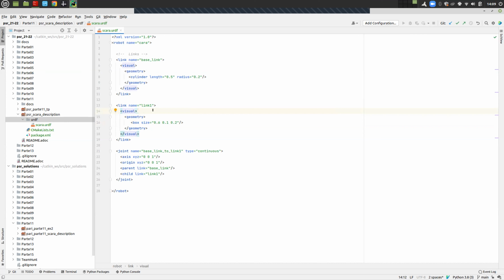So for example, you have some strings like here, which you can pull, and when you pull, it goes like this. And then you have some other strings here, which you can pull, and it goes like this. So this is like a spherical joint, or almost spherical all the way, but this is very hard to do in robots. And not only the actuation itself, but also, for example, the encoder. How would you know the position? You cannot put an encoder in these two axes. So this is not often used in robotics. So we usually find Revolute and Prismatic is more than enough for us.